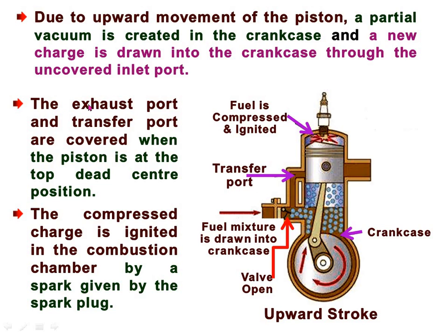Further, the exhaust port and transfer port are covered when the piston is at the top dead center. When the piston reaches the top dead center, both the exhaust port and the transfer port are covered by the piston. The compressed charge is ignited in the combustion chamber by the spark plug. See, this is the spark plug.